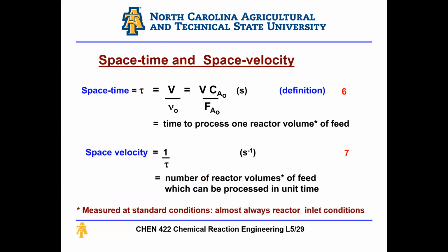Okay, so moving up here to the concept of space time and space velocity, you should also know these equations. Space time is the time to process one reactor volume of feed. The units are seconds. This is your volume, and this is your volumetric flow rate, in meters cubed per time or liters per time, whatever it is. This is your volume, concentration, molar flow rate, volume as well. Just be comfortable with the concept of space time, because it shows up in week number 4 when we're having reactors in series and all this stuff.